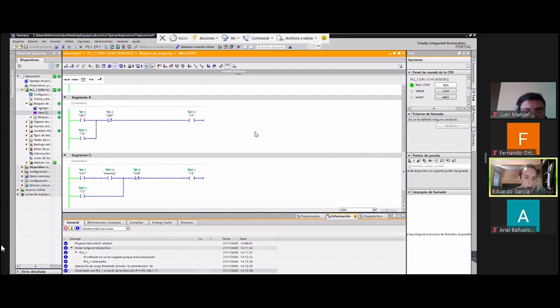In segment 5, we have SA1, the memory, SA0, and J2. SA1 is the sensor of the cylinder when it's extended. The memory is the value that the counter gives us. SA0 is the sensor when the cylinder is retracted. And J2 controls the retraction of the cylinder.